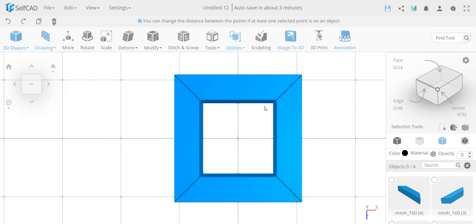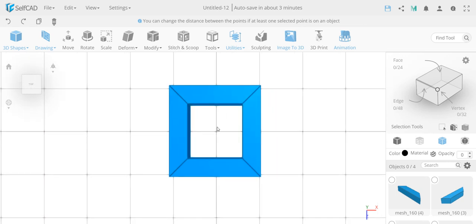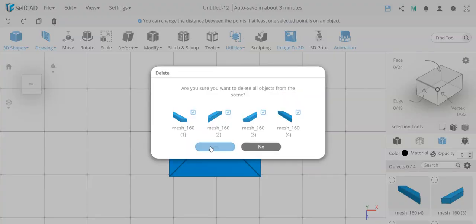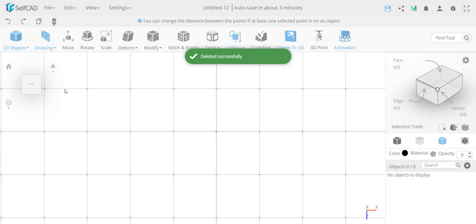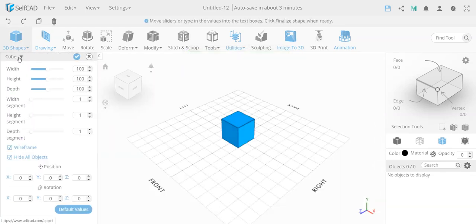If you want to have some odd shapes, I'll show you the other way you can apply the same technique to the shape I just showed, which is basically just scaling faces. So let's get going. I'm going to delete this part. I'm going to go to the cube generator now, so I can enter values. I'm going to enter a value over here, 300, just to show you that you can actually enter larger values than what the slider gives you. The slider is only 200, but you can enter bigger values. And the height, let's say, we'll make 20, the same we did last time. And the depth, let's say 40. I'm just using random numbers. I think let's keep it 60, make it look nice.